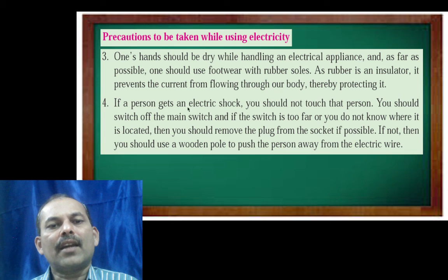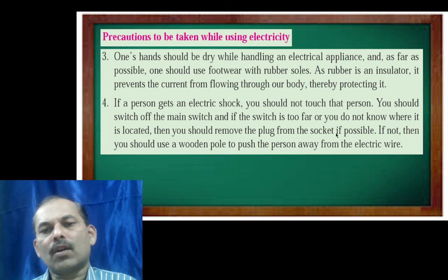If a person gets an electrical shock, you should not touch that person. You should switch off the main switch, and if the switch is too far or you do not know where it is, then you should remove the plug from the socket if possible.